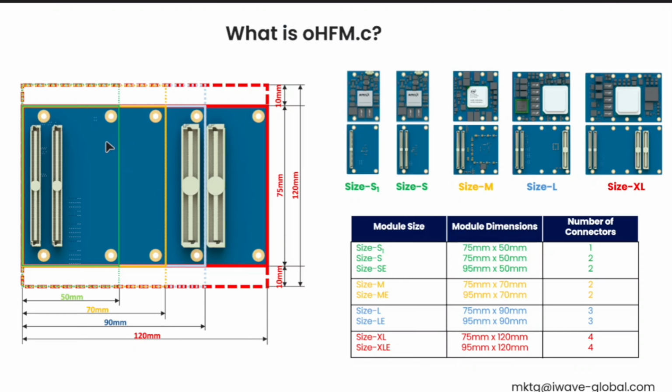As you can see, both support the same sizes, like 75 by 50 mm. But what connector do we use? It is a very dense connector. Each connector supports up to 320 pins. Some of the FPGAs are bigger, and sometimes the SOMs want to have more RAM.